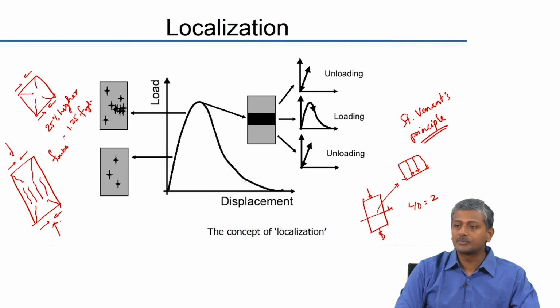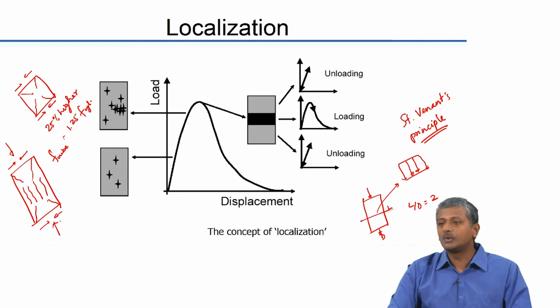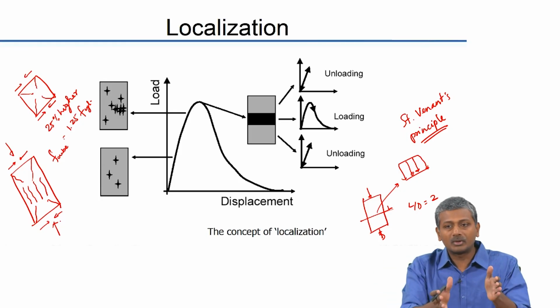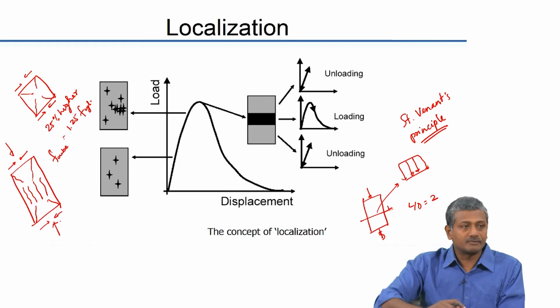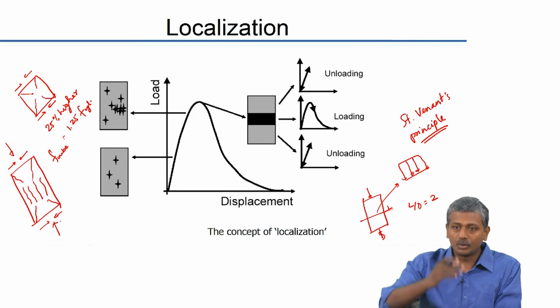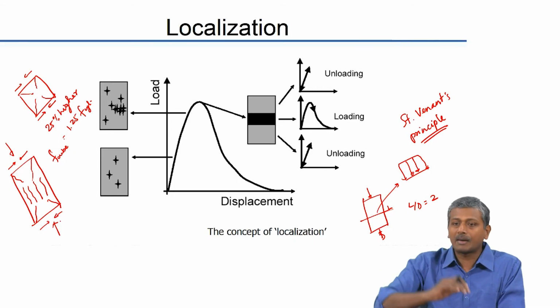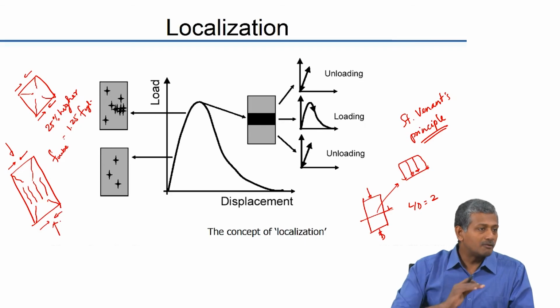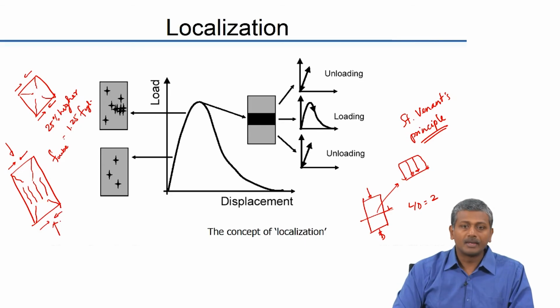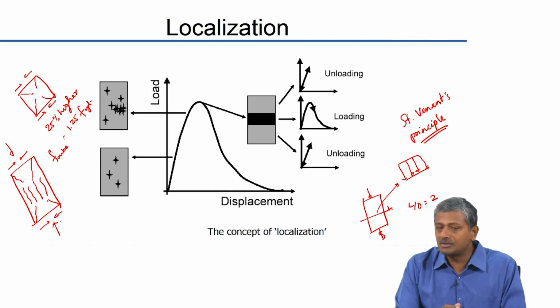We just do a cube strength primarily from the point of view of doing the test easily, because all you need to do is turn the cube on the side and you get a perfectly flat surface. For a cylinder, you have only one way to test it, and you need to cap it properly on the top to ensure that you have a very plain section on the top and bottom. So because of the ease of testing, we test cubes, yes.